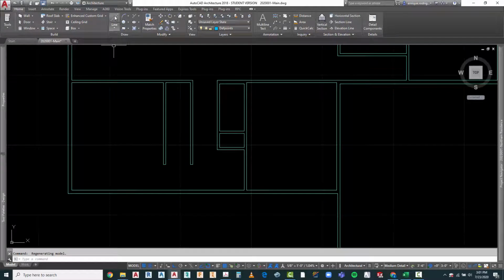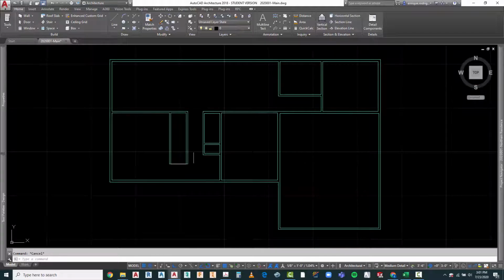So as an example, and you've got to be careful about the layer you're in, so for now I'm just going to go back to layer 0, and some of these things we are obviously going to add specific layers. That indicates the first riser of the stair. So I want to make sure when we draw the basement, or the upper level, that our width here for the stairs is going to be identical, that this bearing wall right at the middle that runs across our house is going to be in the same location as we have it on the basement, and we have some kind of support for the load transfers from the upper level to the main level down to the basement level, obviously down to the ground.